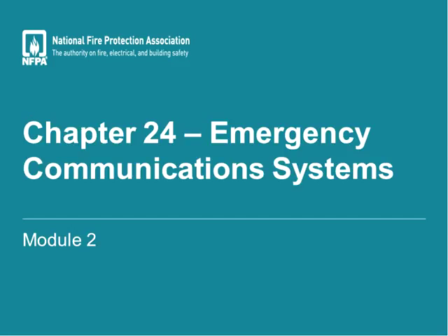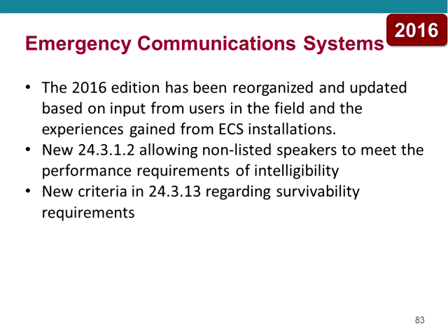Okay. Well, let's go ahead and talk a little bit about ECS, Emergency Communication Systems. Chapter 24 is being reorganized and updated based on a lot of input from users in the field, and experience, and there are some new requirements shown here. We have a new requirement in 24.312 allowing non-listed loudspeakers to meet the performance requirements of intelligibility.